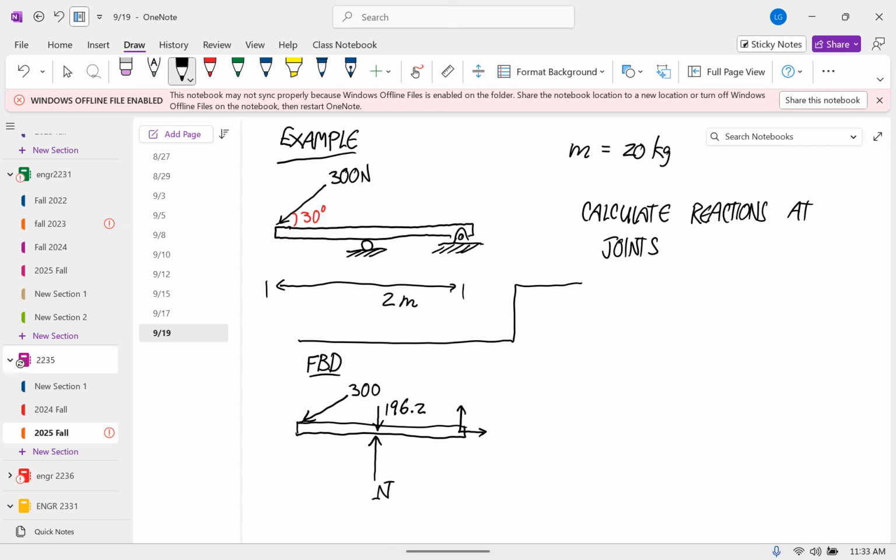Professor, because we're doing statics, and you didn't give us things like rolling friction or whatever, the roller only produces a force upward? Right, only normal. That's a frictionless contact. The roller's basically just there to keep it level, right? Yeah, right. If it wasn't there, that thing would swing down.